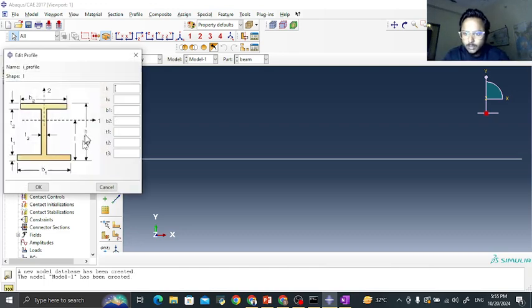Okay, I profile. What are the dimensions? The first dimension is L. L is the centroid distance from the bottom. Centroid distance is half of the total height, that is 100 mm, 0.1 meter, and the total height is 200 mm, that means 0.2 meter. Width is 100, so 0.1. Second width is also 0.1. Thickness everywhere is the same, 0.02.